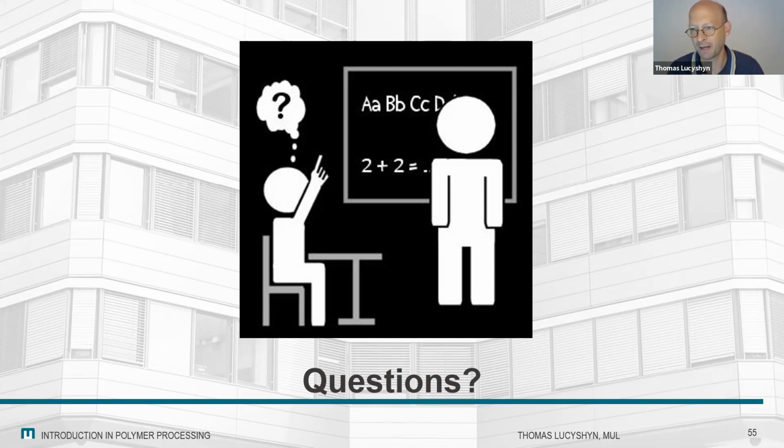But in the final product, if it's a very compact part for injection molding, for example, there will not be too much surface where you can extract something from it. So I would say it's more maybe in the stage after compounding, when you have pellets before you go for the real production process. This would be a good point where you could maybe add some washing process. But in the final product, I'm afraid it's not so effective to do some washing of the product.